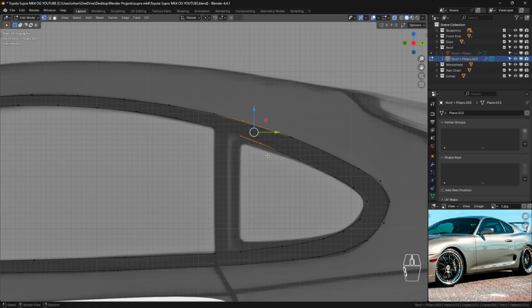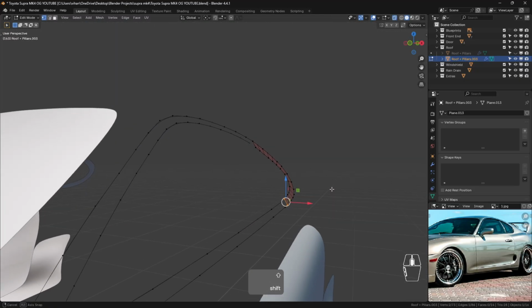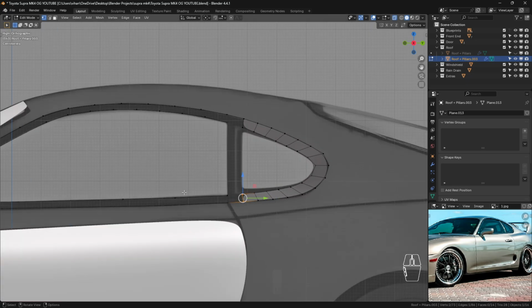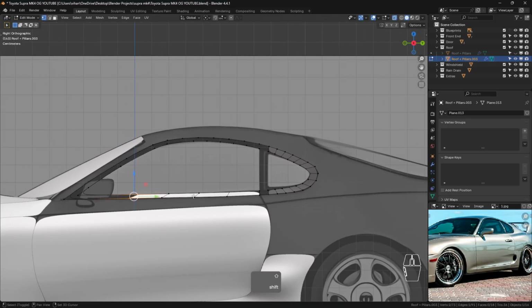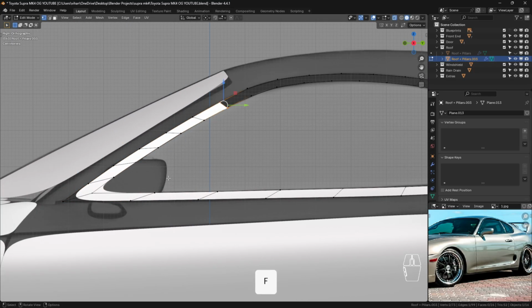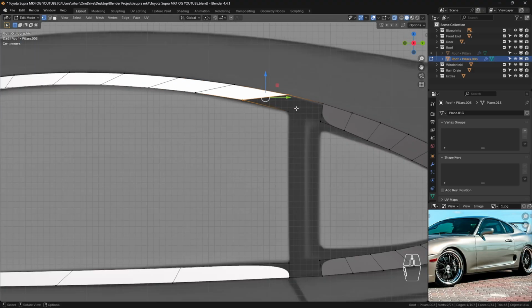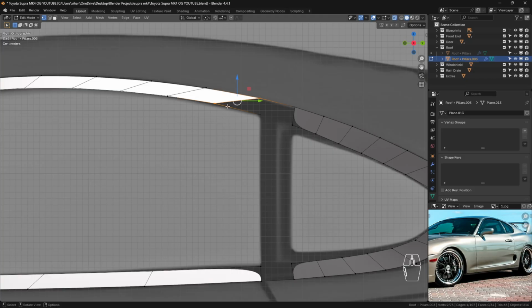And now what we're going to be doing is facing this up. So just do the same thing that I've been doing. Then select these two, F. Just keep pressing F till you reach here. Alright. After done with that, then we're going to be facing these parts up. Alright. And just keep pressing F. So it's going to keep going automatically. And F again. And it seems like we have an extra vertex right here, or one less here.